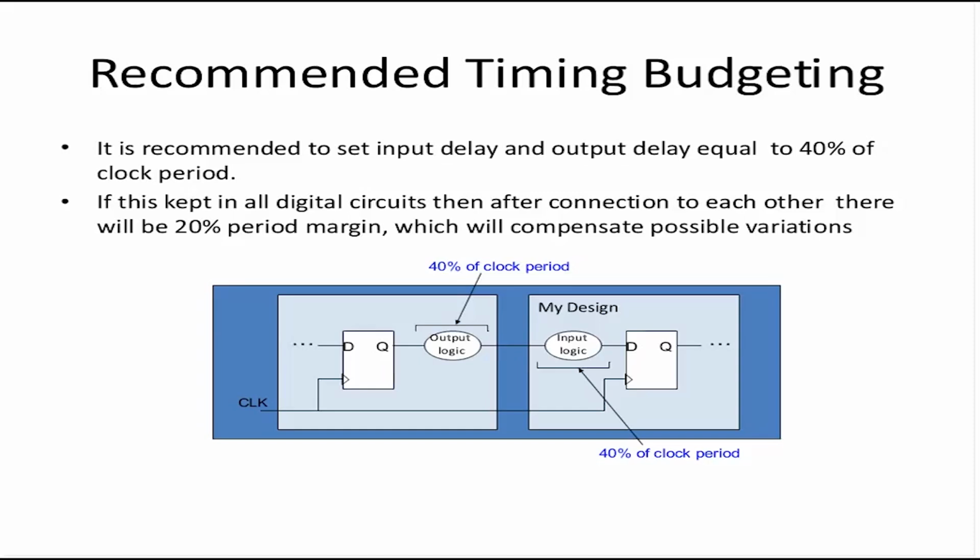So now Design Compiler knows that the constraint from the input port to the first sequential element is that it should not consume more than 6 nanoseconds. This is how the input to register paths are constrained. I'll have a lot of these types of equations in unit 5 that will make things much more clear, because static timing analysis is much more extensive than the optimization constraints used by Design Compiler. Since Design Compiler is only focused on performance, it needs to know what the goal is.